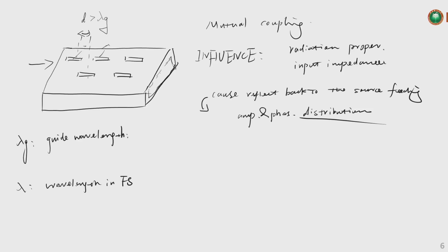For such a specific mode, or the dominant mode, usually we set the lowest mode because we want to get the maximum energy propagation inside of the waveguide. So this is related to the wavelength of the dominant mode, or for the highest energy output is the lowest order of the mode.